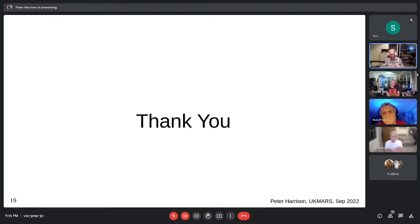So, for example, if you've got a profile where I've left the slide on because I've got some more to do. If you run up fast and hard towards a turn and then come down to turning speed, it's very unlikely you will have overshot the turning point. Right?